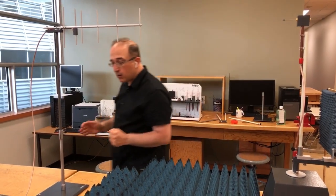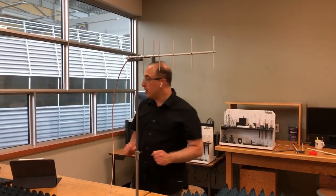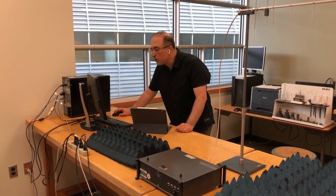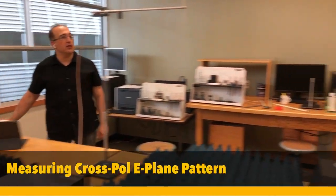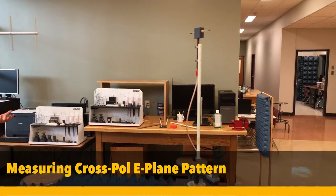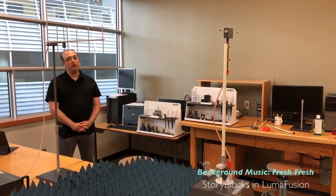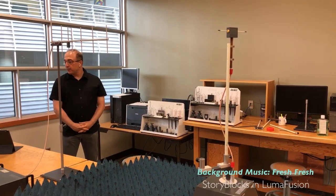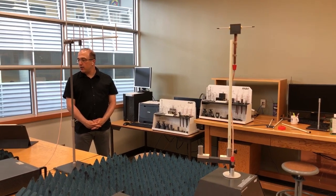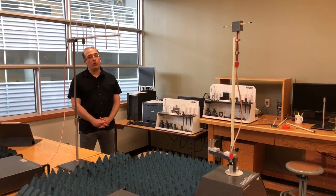So let me start the RF generator. So now I'm gonna go to the software, and I'm gonna go to the acquisition, and I'm gonna start the acquisition. So as you'll see, it is still gonna rotate similar to co-pole E-plane. And at the end, we need to look at the signal and see how cross-pole pattern is compared to co-pole pattern.